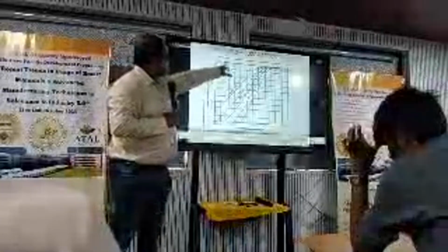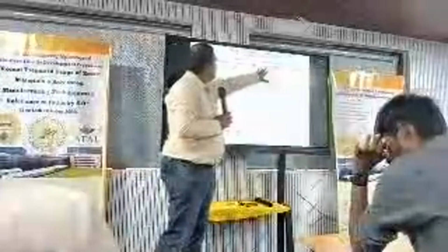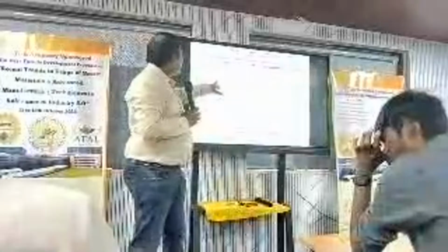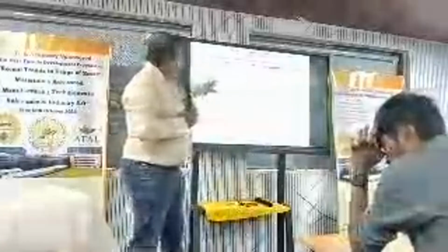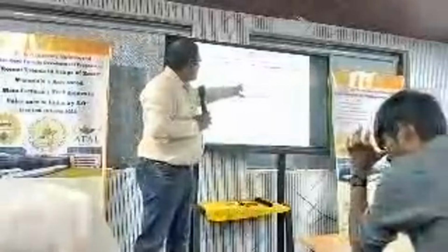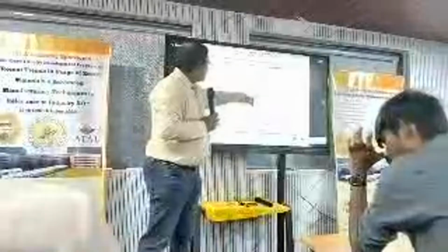So if you see, this is the nomogram. We want to design, because this is the loss factor, this is the thickness ratio, and this is the Young's modulus ratio. So our aim is that the loss factor should be as high as possible. So ladies and gentlemen, I want this graph, this line. Basically it is not possible because it is very, very high. Ladies and gentlemen, I want eta by eta 2 to be 0.1. Then in that case, you can select either this graph or this graph.